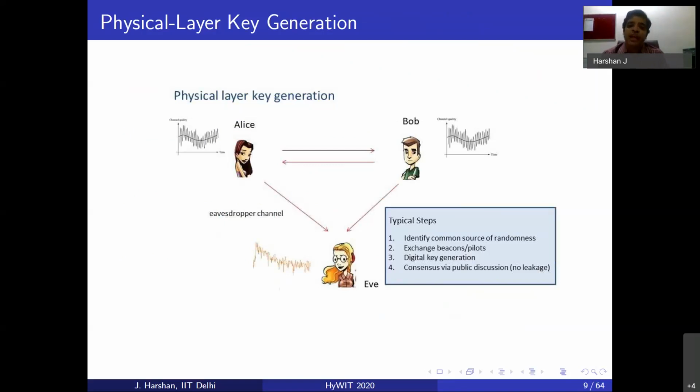So this is exploration. What they do in this idea is, Alice and Bob are going to transmit to each other pilot symbols. These are called probing symbols. These are known symbols to each other, and as a result they are going to observe the channel between each other, right? And then if they keep doing this for some time, they will be able to witness the variations in the temporal randomness offered by the wireless channel, and that is one of the important steps here, because just with the process of sharing pilot symbols within a given time slot in what is called a time division duplex manner, they can actually witness a source of randomness over time, and then eventually that could be used to harvest a secret key.